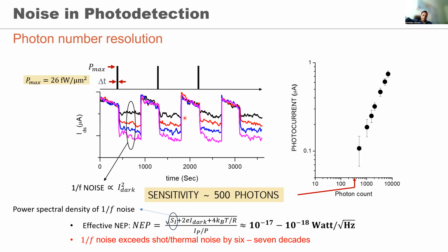Once you reach the steady state of the operation of these devices, then there is no stochastic behavior at the time scales of these experiments. So you can see this in seconds, right? The seconds are about 10, 12 orders of magnitude slower than the recombination time scale that is happening of electrons jumping out of graphene into the molybdenum disulfide layer.